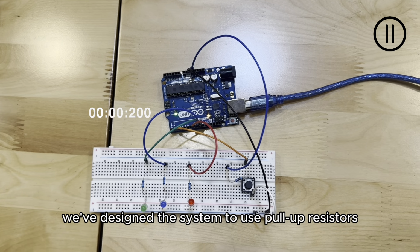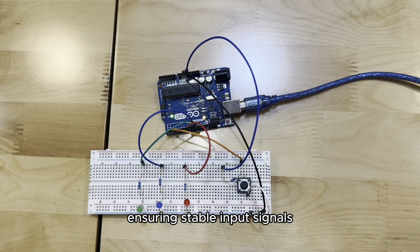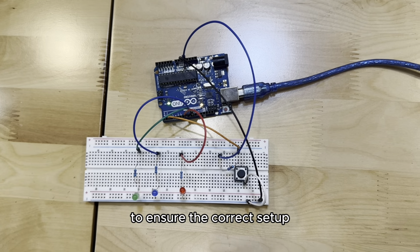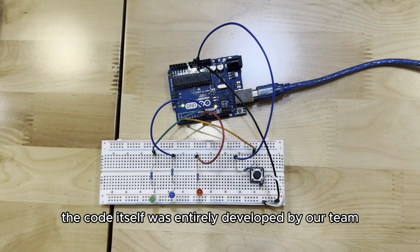We've designed the system to use pull-up resistors on our buttons to avoid floating states, ensuring stable input signals. We derived the pull-up resistor configuration and obtained the Morse code from online sources to ensure the correct setup. The code itself was entirely developed by our team.